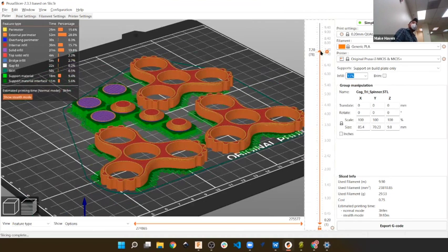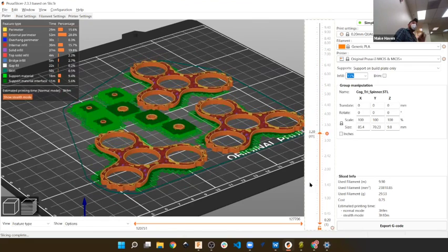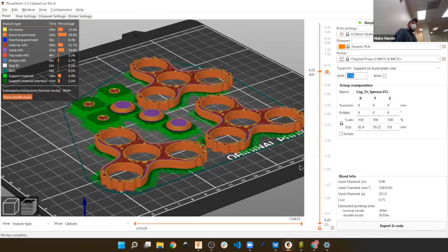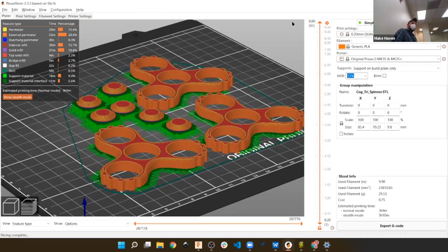A lot of 3D designers, 3D printers will make their designs so that they are 3D printable without supports. And I think that's probably true about this design. If I flip those over, the angle is probably just the right one so that I could print them upside down without a problem. But it was easy enough to print them with supports in this way.